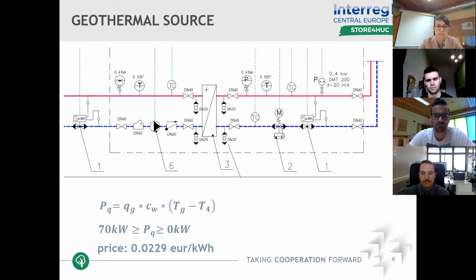and then for instance you would be able to survive even for lower temperatures than -5, because you would pump in advance your storage and then figure out how not to use the oil boiler. So the availability of this temperature, the temperature profile of the primary side, would be very good to know, as a prediction of when you can draw the energy from the network and when you cannot.